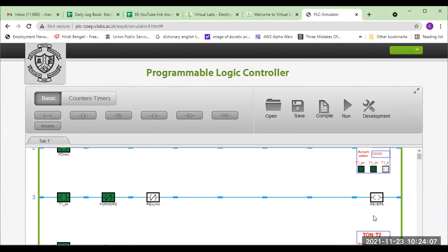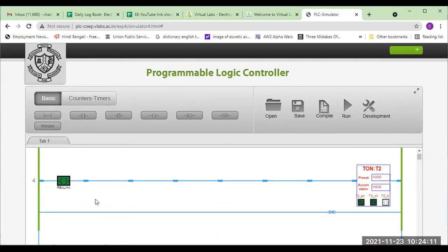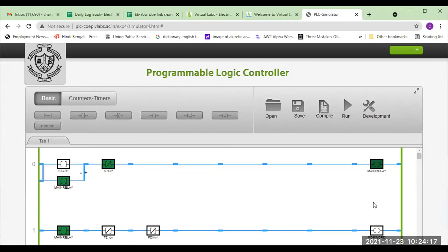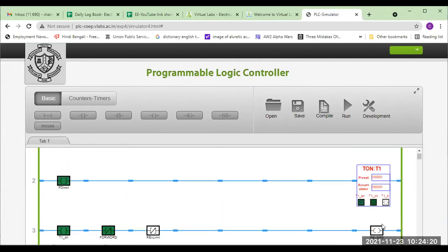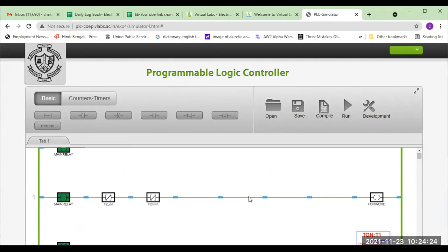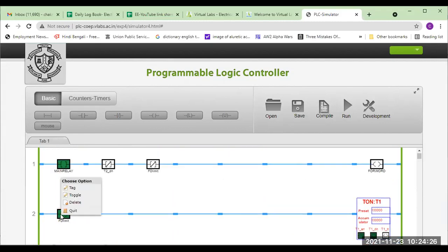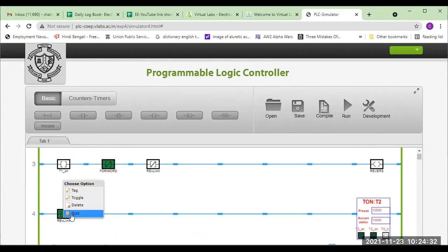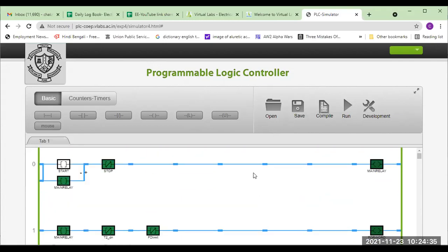If you give motion, it will go out of the rail. So it is counting. Yes, after some counting, the done bit is reached. Then again you can see the main rail is there, and again it will start cycling. So you have to release this forward limit, otherwise it will not start, and this reverse limit, then your motor will start again.